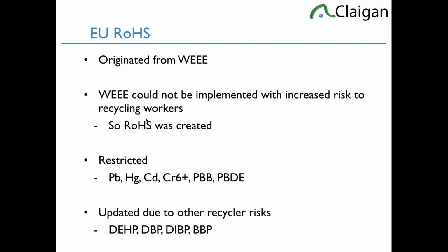environment. So there are more substances going through this consultation process now, MCCPs and tetrabromobisphenol A. Most of them won't make it through. Where they've been limited is that the chemicals they're choosing are ones that were REACH registered as chemicals that indicated a use in electronics. So anything that's a significant hazard, or they believed it is, is going through consultation for being added to RoHS. Unfortunately, it's use at the chemical level as opposed to product level, where most of them, like tetrabromobisphenol A, are fully reacted and are not really present in the final product.